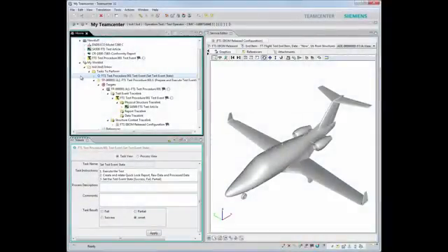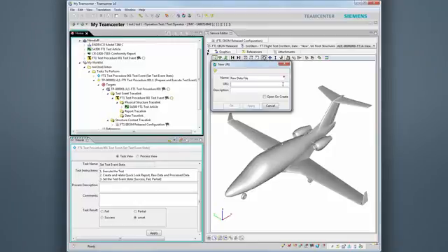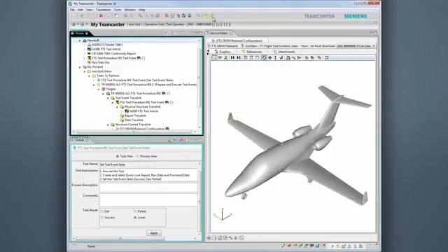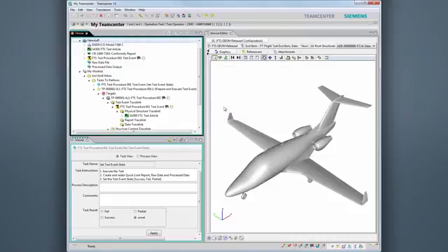After the ITRR approval, the test operator has all of the approval data, including the test procedure, the test article configuration with instruments, the associated channel numbers, and other data required to execute the test. During the test execution, the raw data is recorded from all of the measuring instruments. The calibration information for each instrument is used to generate the processed data from the raw data. Next, data trace links between the raw data and processed output with test event are created.